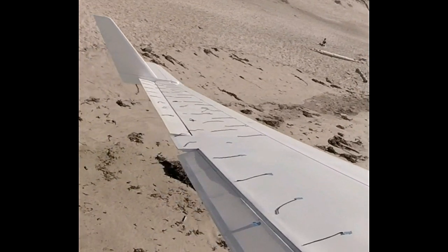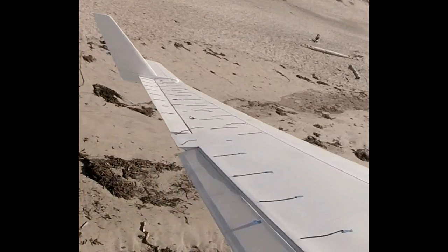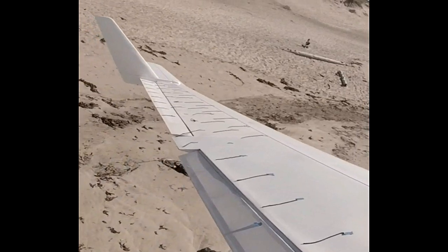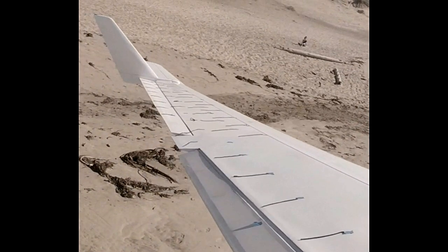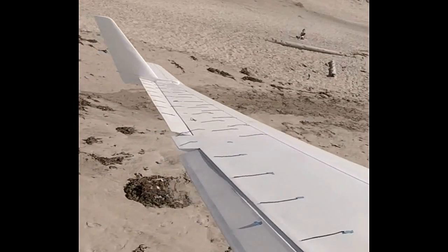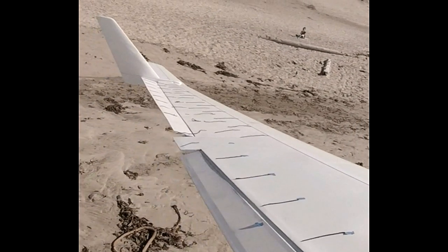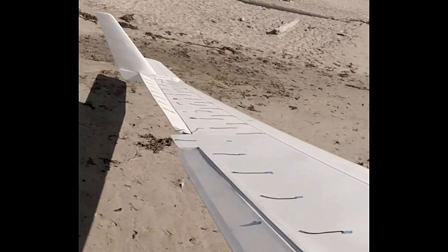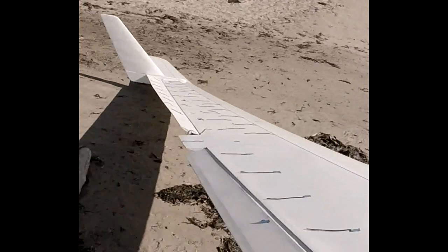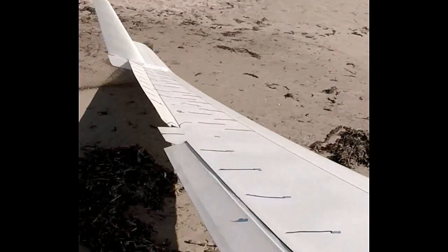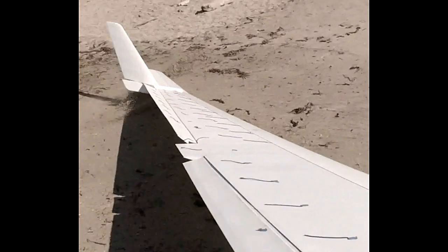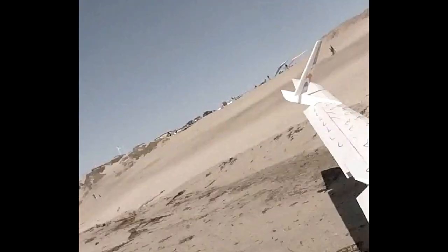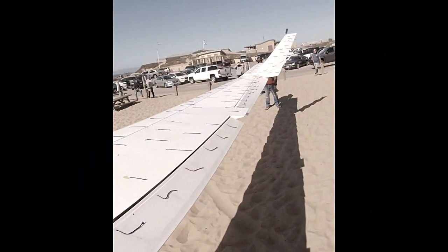There's another stall starting there, and I do think that the stalls are predicated, I don't know, is that the right word? The stalls are started by the flow separating off the elevon. If we keep the flow attached to the elevon, I shouldn't have a problem with those early stalls like that. A little more up elevator as I attempt to land, and then the landing's hot, and this is where I tore all of the down tubes off the pilot's cage. I think you'll see me fly into frame here in a second. Nope, we didn't get to see that.